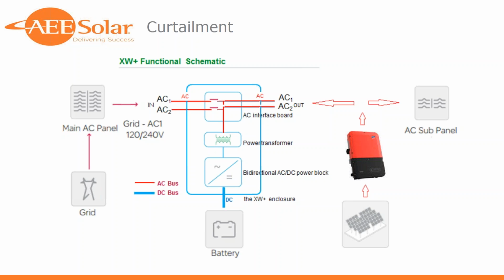They put in a battery inverter and a really small battery bank. The end result was that on sunny days, the batteries would top off very quickly. The system would power loads for a period of 20 to 30 minutes. The battery would drop back into the bulk stage. The battery inverter would then try to tell the PV inverter to start up again. Sends out a qualified grid signal to the PV inverters, and those guys have to wait 5 minutes as required by UL 1741. That 5 minutes waiting for the PV inverter to start up would drop that bank below low battery cutout, and the whole system would power down.